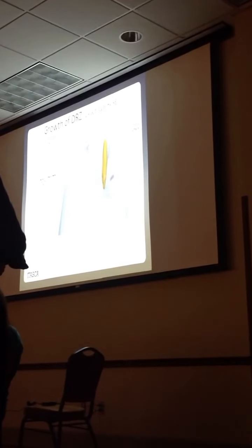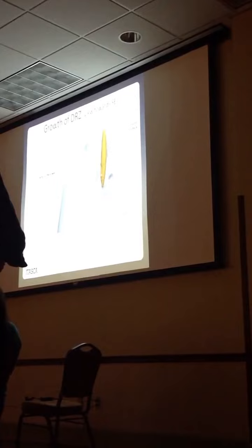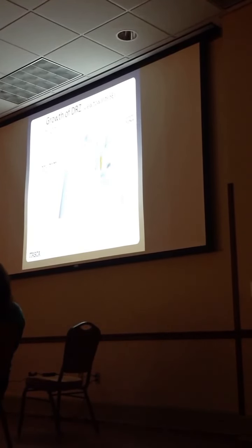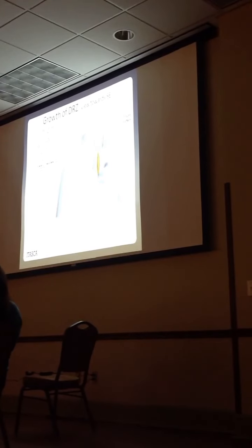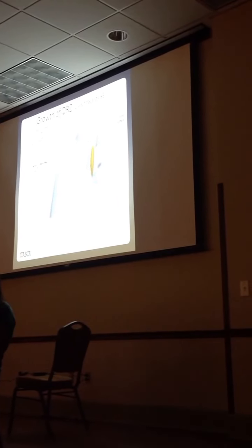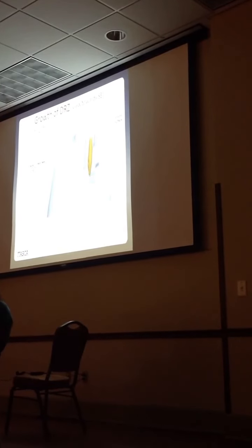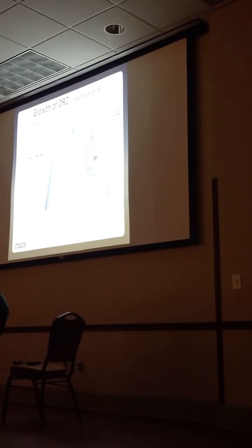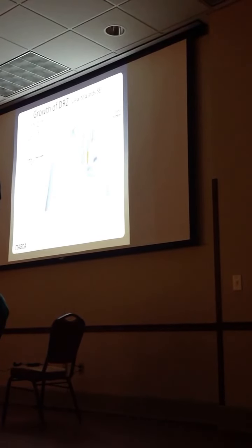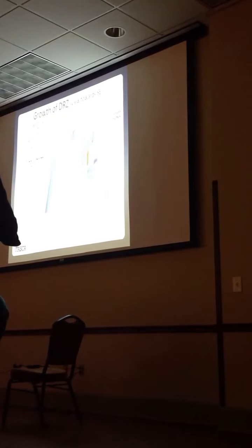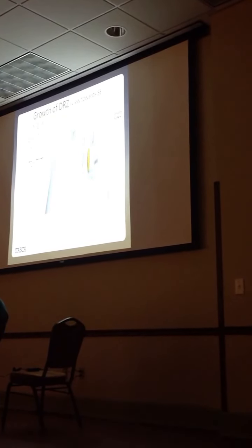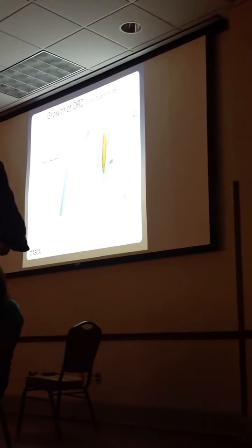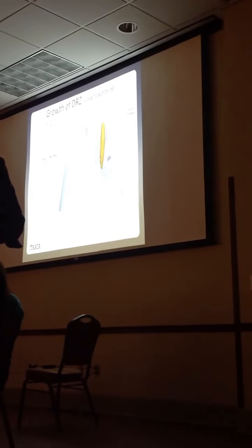What happens is the sidewall of the cavern collapses in, and in that collapse, it removes volume from the rock immediately adjacent to the cavern, and that rock breaks up, and that creates a chain reaction. That chain reaction creates what we're calling a disturbed rock zone that propagates all the way up to the surface. And as it reaches the surface, it creates a sinkhole. So the sinkhole is really the surface expression of this highly damaged rock volume that reaches the surface.